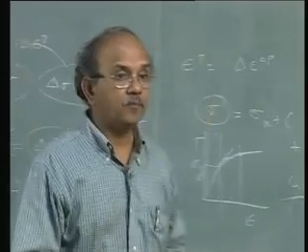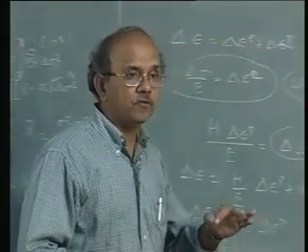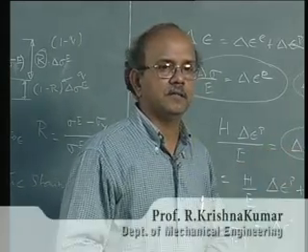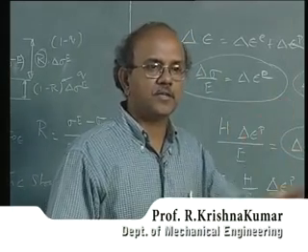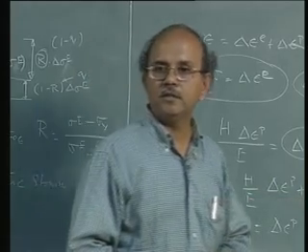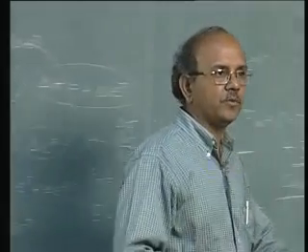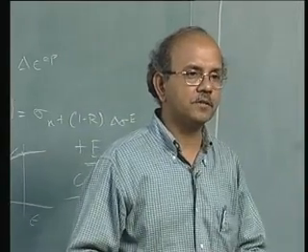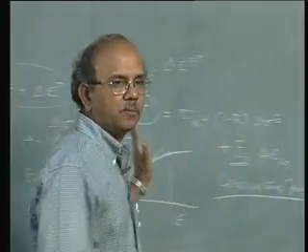Note that if I am only in the elastic case and moving from elastic to elastic, my predictor is the actual value. So, I will have to update the stress only using the elastic constitutive equation, and so I can move ahead in the same fashion without calculating all the plastic part.